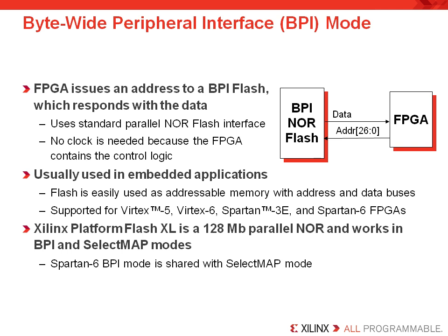In BPI mode, the FPGA configures from a standard parallel NOR flash PROM. The BPI configuration interface is primarily designed to support standard parallel NOR flash PROMs. The interface supports both byte-wide, that is x8, and byte-wide half-word, x8 and x16 PROMs. The BPI interface can work with other asynchronous memories that use a smaller SRAM-style interface, such as SRAM, NVRAM, E2PROM, EEPROM, or a masked ROM.